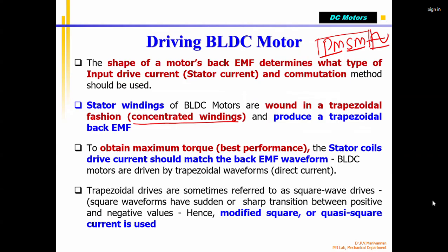That means the magnetic field created in the air gap will be very smooth. Already we discussed that. So the torque will be less, but a smooth torque curve and all those things are better; that is the drawback. But if you want more torque for the given voltage, you will go for the BLDC motor. The BLDC motor creates a little torque ripple when you operate at low frequency. When you go to high frequency, the ripple will not be there.